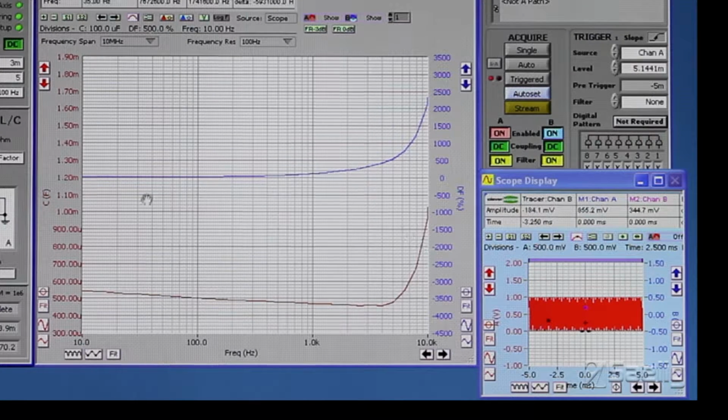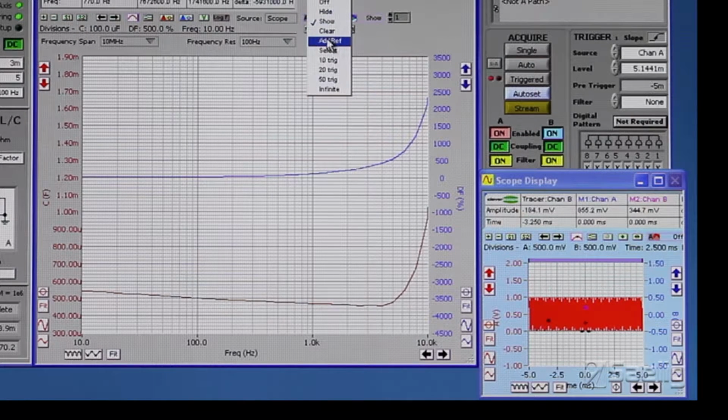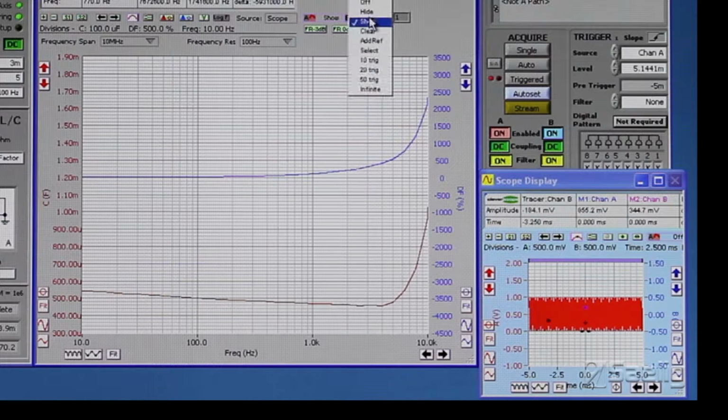So that auto-sized. The first thing we're going to do is remember to click off auto setup up there. Okay, so here, what I'm going to do is click this, which is normalizing the scales to the graph. And then I'm going to save this by first clicking Add Reference here, and then Add Reference there. Okay, so now we've basically saved these two.